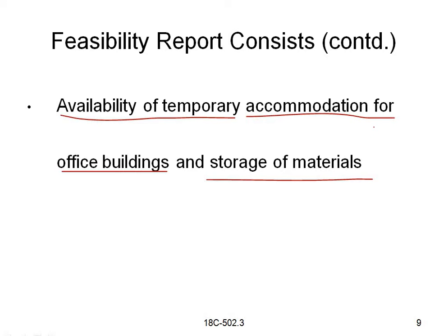At the construction site we construct temporary sheds or godowns for storage of materials, and office buildings should also be constructed at the site as temporary buildings, because the files, bills, registers and employee details will be kept in the office buildings. Storage of materials is also very important, how the materials should be stored and what materials are required should be prepared in the feasibility report.